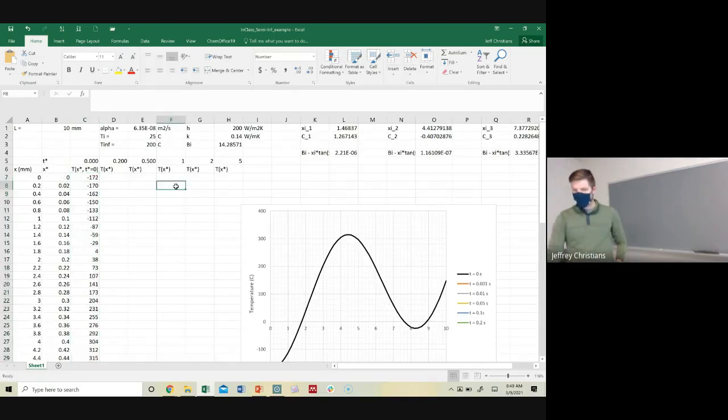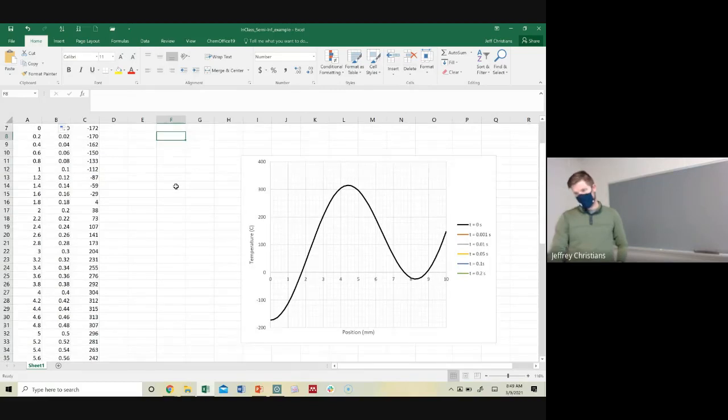Okay, so we have 3 terms, and now we're a little bit better, I guess. We're trying to be at 25C, a flat line. You can see we're maybe a little closer. On average, we're now curvy around 25, but it's still pretty terrible. Again, that's because we're trying to replicate something where we would need all of the terms, and we're just using 3. As we kept adding more, we would dampen out those wiggles, and it would just be a wiggly thing around 25. But initial conditions are where this model is really terrible.